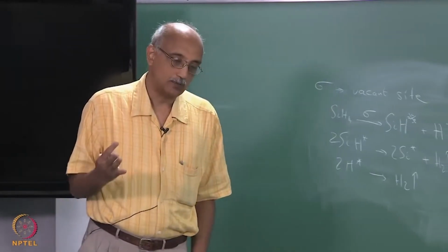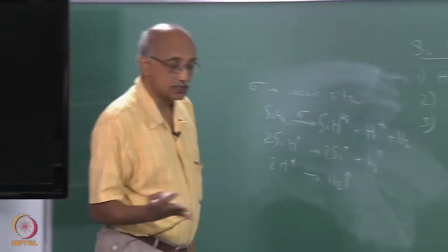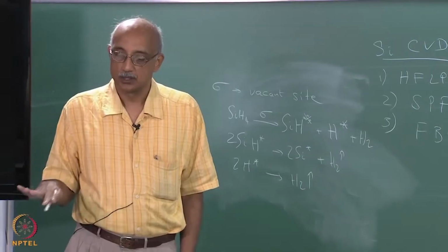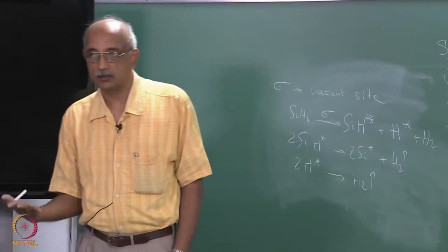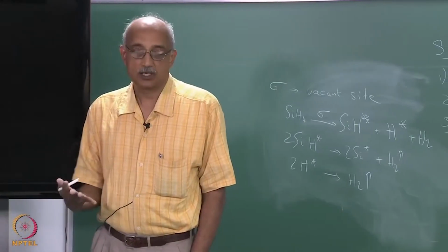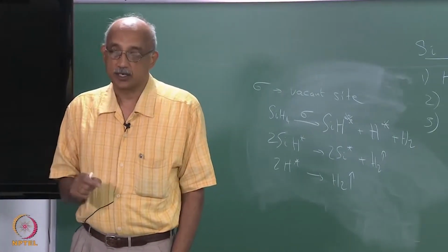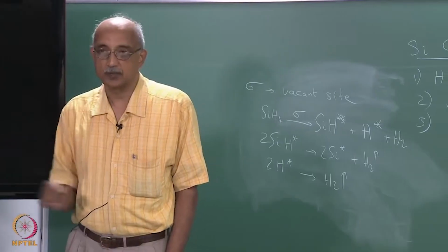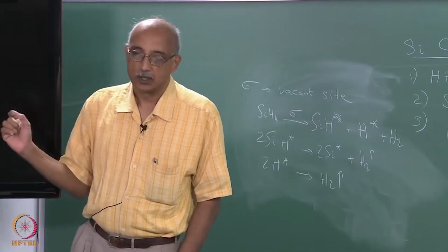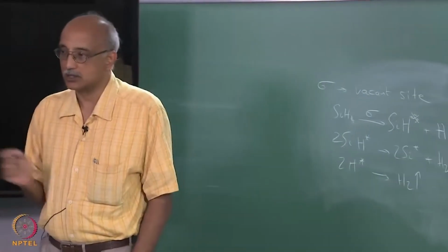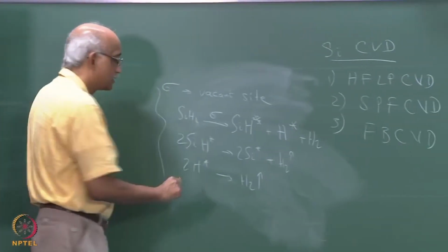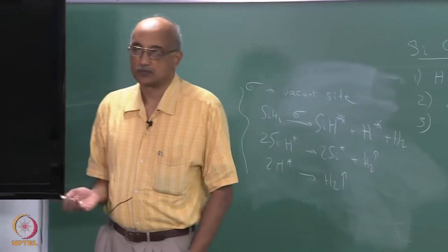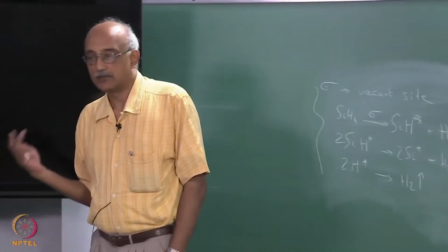It is based upon very extensive investigations of the surface on a real time basis. Essentially, you take the surface, expose it to silane gas, and observe what species get adsorbed and what is the time dependent behavior, how stable are they, how do they migrate, how do they cluster, and so on. So, describing this, as I said, is a separate science all on its own. You really have to have a very good understanding.